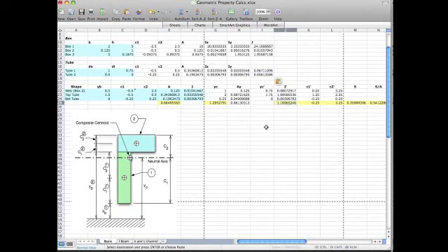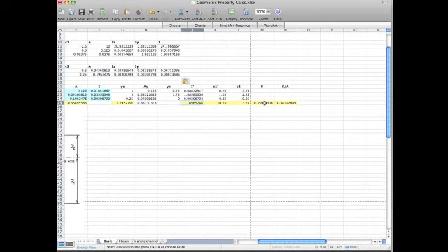And then it'll get you the I. And now here I'm just talking about the I about the neutral axis. This is really the IY. About the neutral axis, and then the outer fiber distance from the neutral axis. And also I'm computing the shape factor, which is the I over the maximum C1 or C2, and then also the shape function.